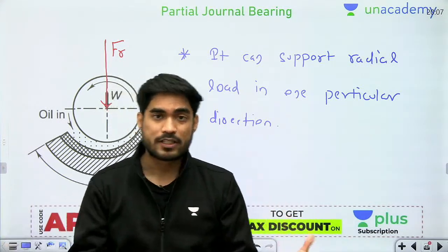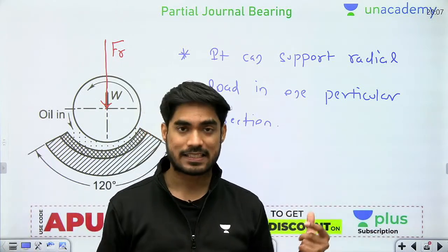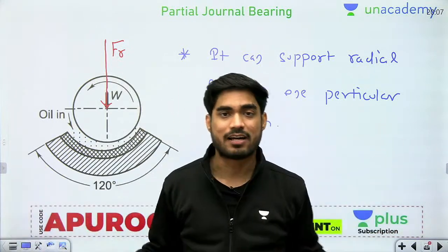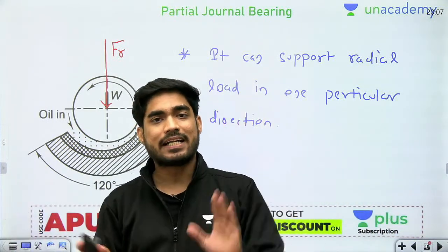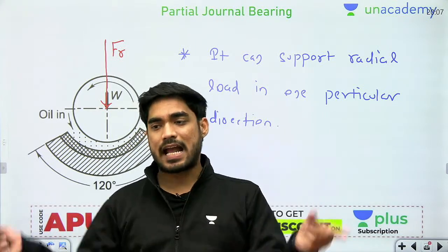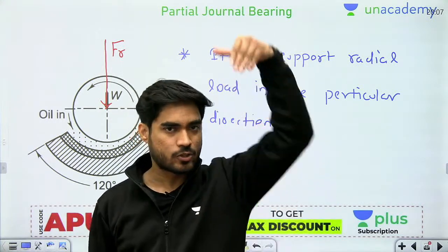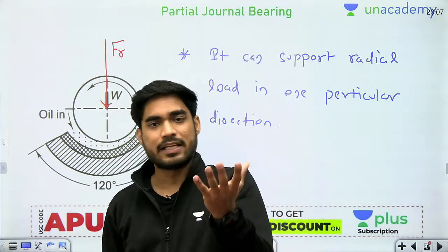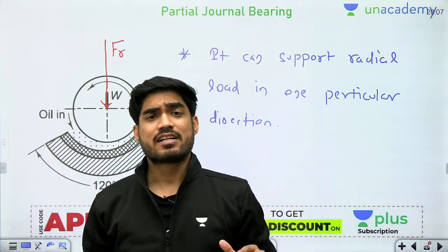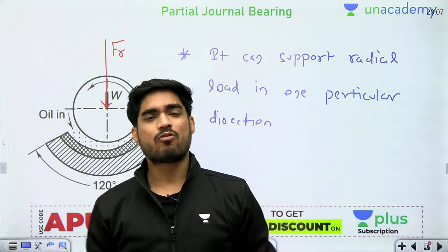जो व्हील्स को सपोर्ट देने के लिए, व्हील के वेट को सपोर्ट देने के लिए यूज हो रहे हैं, दे आर नोन एज एक्सेल्स. बट शाफ्ट्स आर ट्रांसफरिंग पावर, एंड ड्यूरिंग दिस ट्रांसफर ऑफ पावर, रेडियल लोड कैन बी अप्लाइड इन एनी डायरेक्शन. Even if you are using a belt drive or chain drive or gear drive, radial load are in any direction. It is not particularly in vertical direction. But in case of axles, axles are supporting only the weight of the wheels. So beta, in that case, the load will be only in vertical direction.